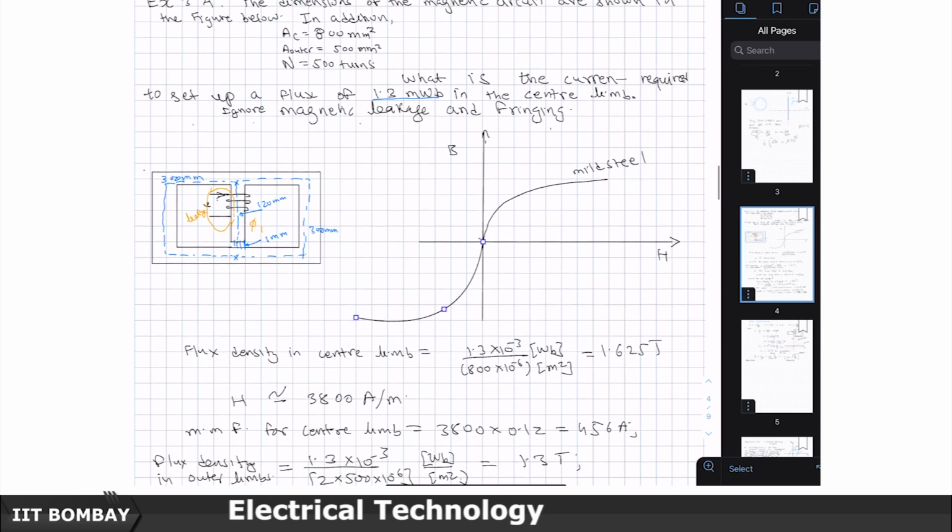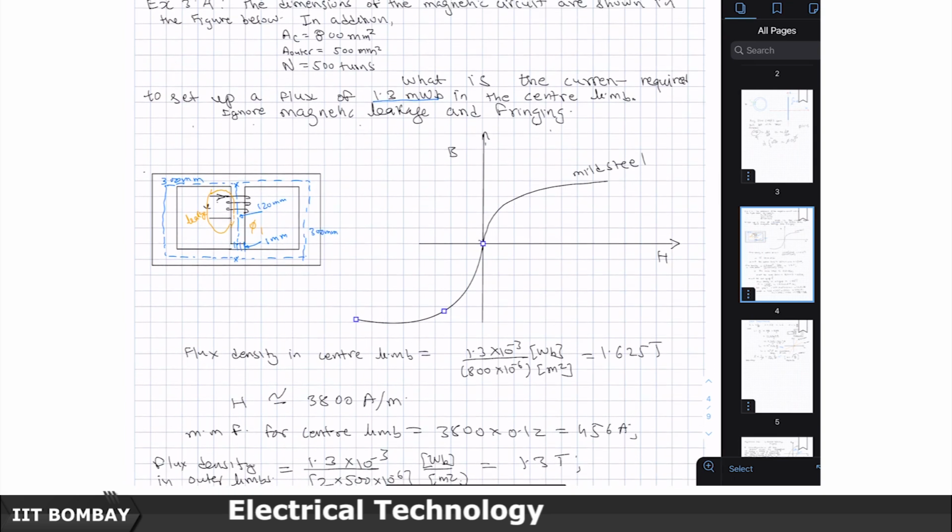And what is going to happen is, I told you that there are magnetic dipoles and they will keep on aligning as I keep increasing H in this direction. More and more dipoles will be forced to align with respect to the applied field, and so the B will initially tend to increase linearly, but afterwards a saturation effect will start coming in.